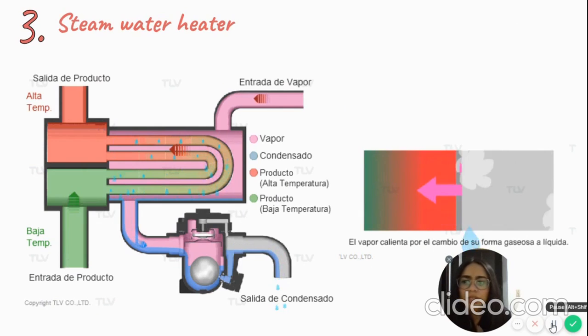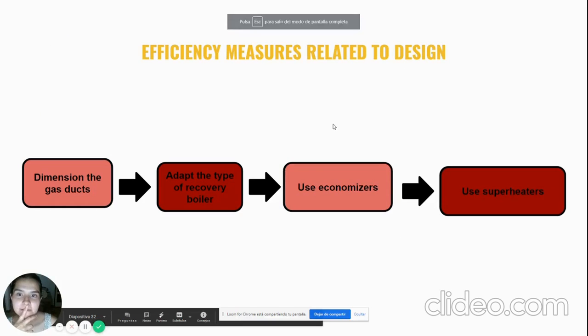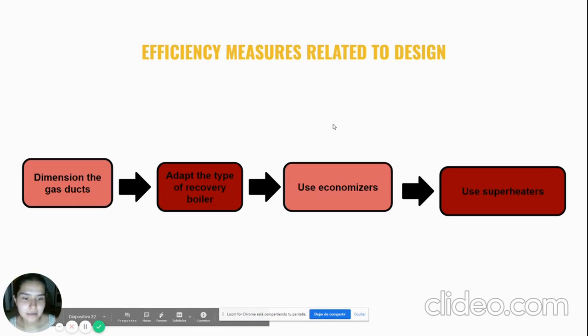Steam water heat. Low pressure steam can be used to make hot water for process or domestic use. If the supply of steam from a waste heat source is not continuous, the supply of steam can be kept constant by using a supplementary steam valve. Hot water supply for the food industry, chemical and pharmaceutical manufacturing, and building technology.